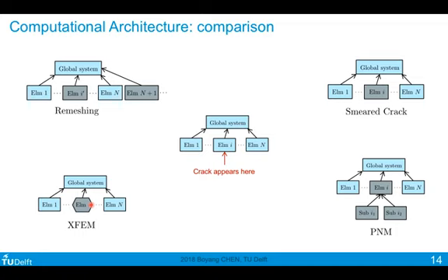In the phantom node method, the approach is that you add a sublayer underneath your original element, where you have two sub-elements, and you perform the integration on the sub-element level, and then you assemble these two sub-elements into your original element I, and then you assemble again to the global system. So you have one more level of hierarchy in the phantom node method. So this is an overview of the difference at a more abstract structural level.